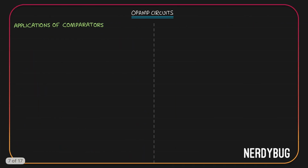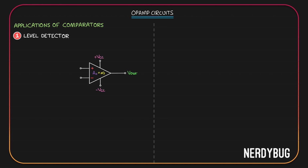Let us now learn some applications of comparators. The first one is a level detector. It detects whether an input signal is above a particular voltage or below it. For that, we need an Opamp. Let's give the input at the non-inverting terminal. I'll take a voltage divider for the reference voltage and connect it to the inverting terminal. This is the same circuit that we just discussed.